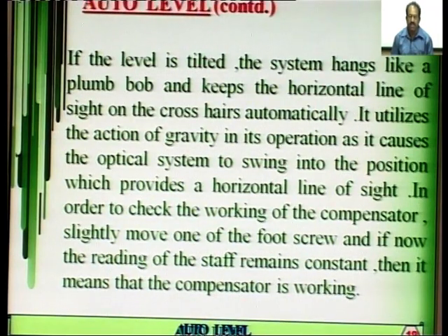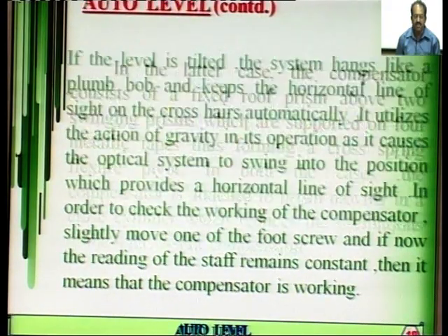In order to check the working of the compensator, slightly move one of the foot screws which we have on the level, and if the reading of the staff remains constant, then it means that the compensator is working.